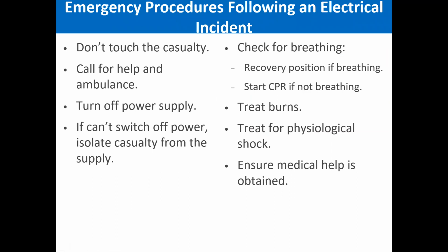Okay, what emergency procedures should be followed in an electrical incident? Very, very important: never ever touch the casualty. If you suspect that somebody has received an electrical shock or has undergone an electrical incident, you should never touch the casualty. Call for the ambulance. Then you should turn off the power supply. Identify where the power supply is and turn it off.